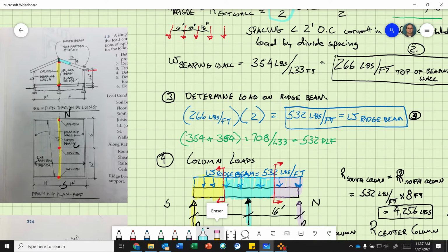So the roof is held up by the ridge board, and then the ridge beam, and then the columns hold the ridge beam, and now we're down to the floor beam. Okay, so we still have to get the walls down to the top of the foundation wall yet.